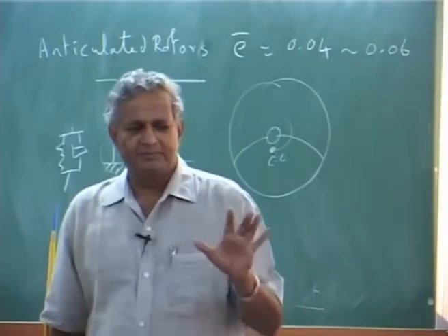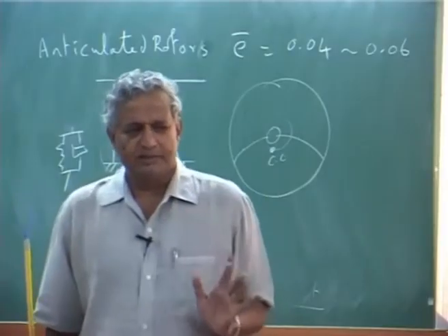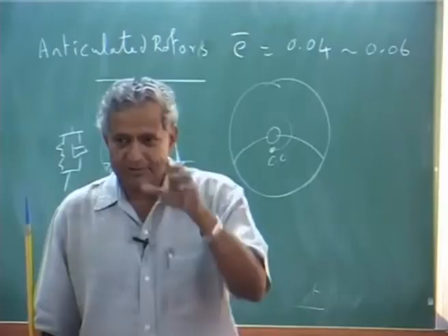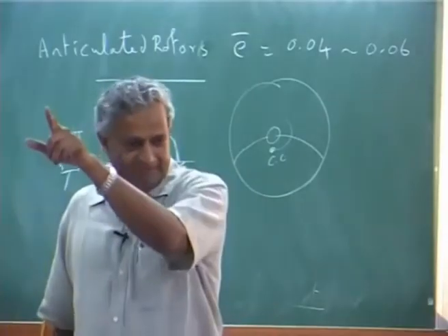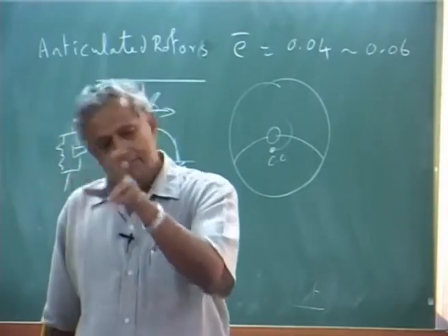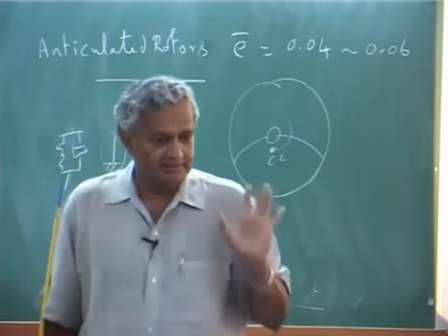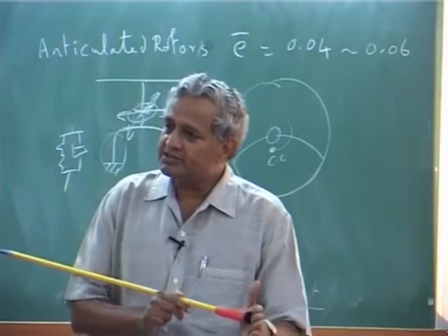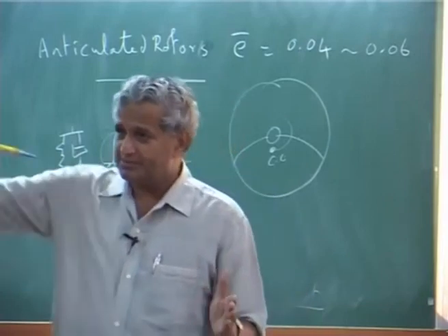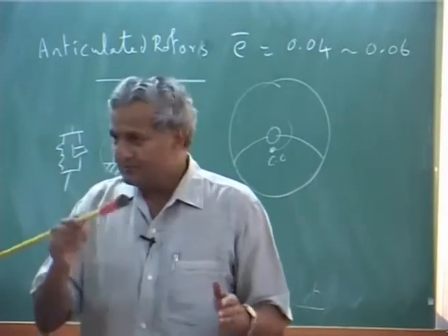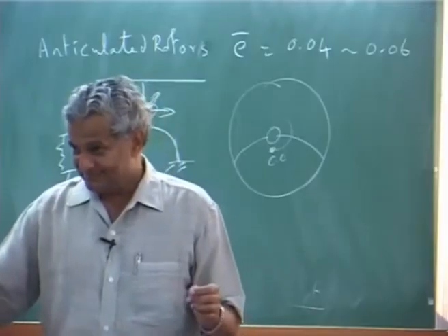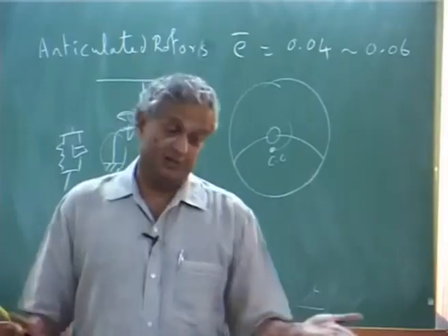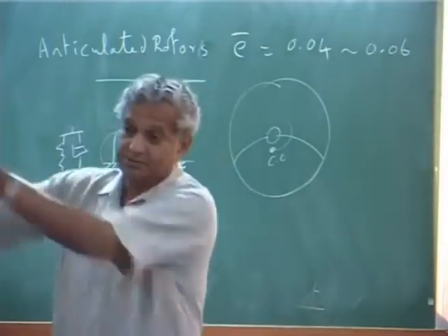In the fixed frame, physics is okay, CG is moving, that is all, but you have to know at what operating rotor RPM that really hits it, and then you avoid that. Okay. But your rotor RPM always starts from 0 to 100%. Definitely you may cross the resonance point,